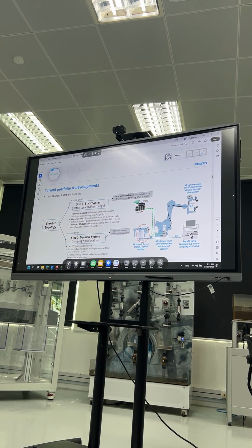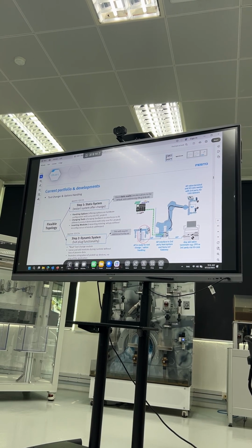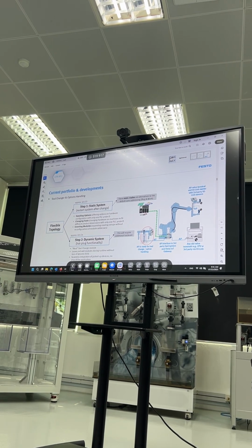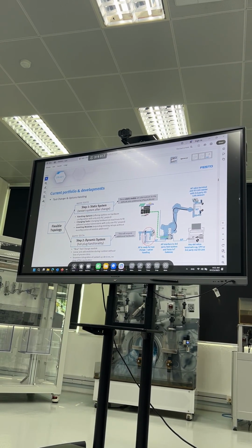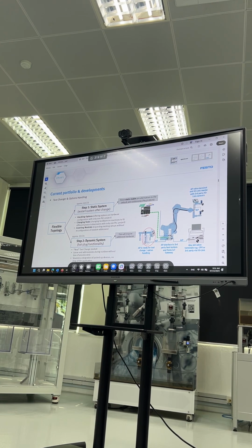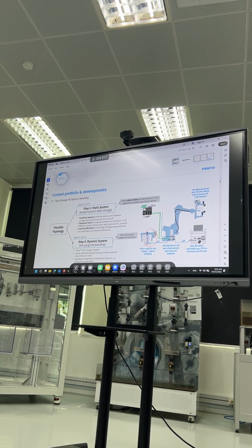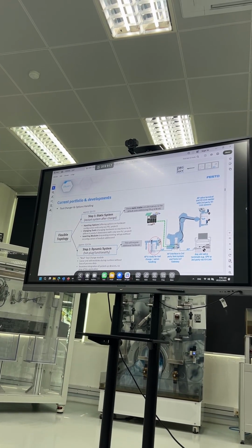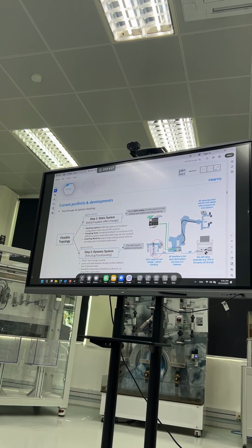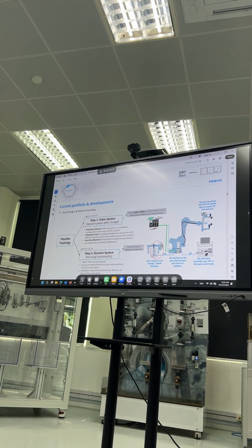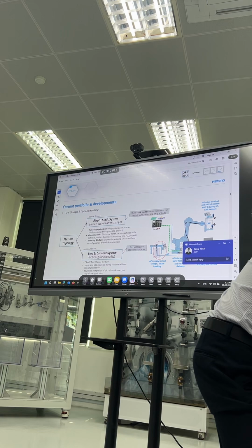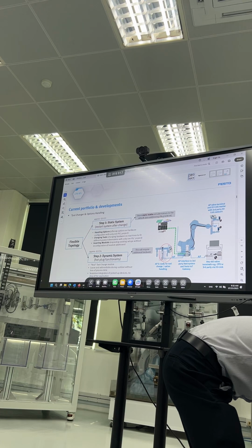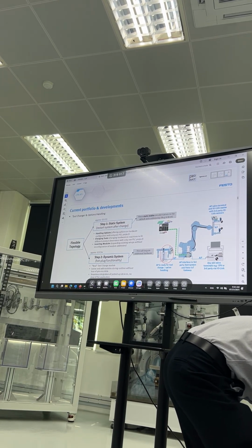Then they have a very far decentralized remote I/O module, and they don't need, let's say for example if they are using CPX API, they need a few bus interfaces in each of the locations, right? But for CPX API you don't need that. You only need one fieldbus interface, and then you can have the I/O modules at different places. Sorry, it's not the total length of 80 modules. Between this first module and the second module, it's 50 meters. So you can have 50 meters to here, and then another 50 meters to another module.